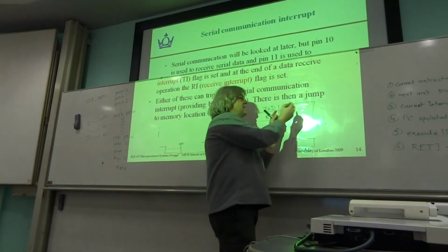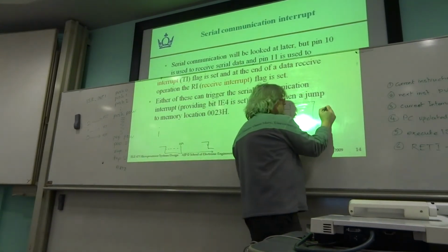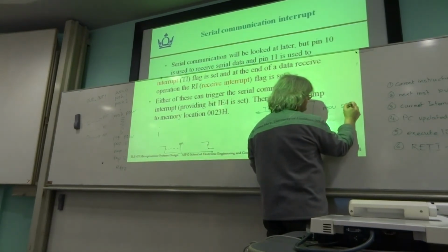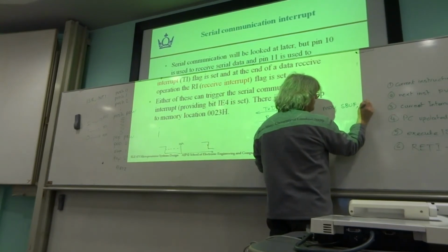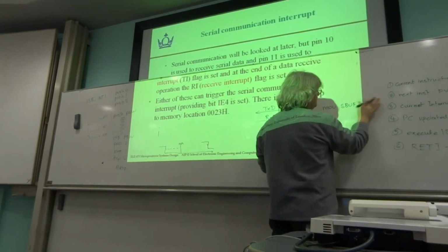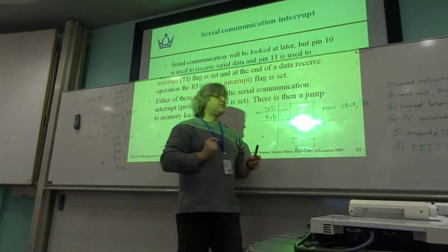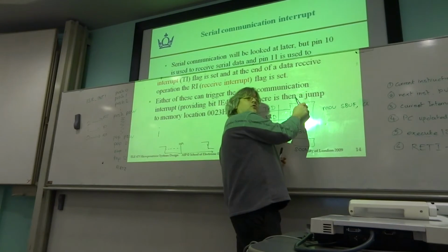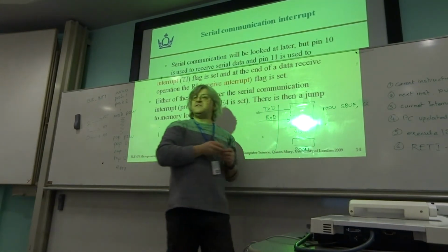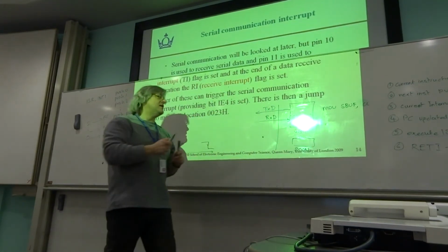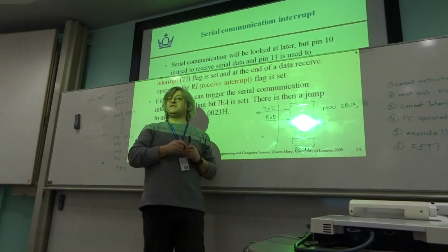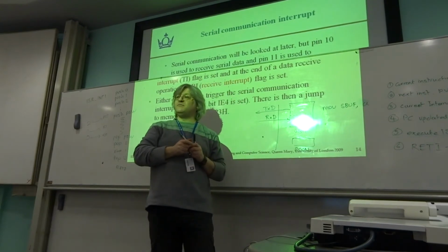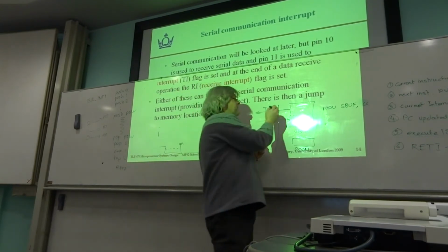If anything needs to be sent, all you do is move into SBUF the contents of the accumulator, for example. So if something was in the accumulator, you stick it in here, and that will automatically be transmitted. You don't have to tell it to transmit. That's why we use this hardware support on the serial interface. It's quite nice. It will also clock out the bits at the appropriate rate that you've configured, but we haven't done configuring the serial interface yet.